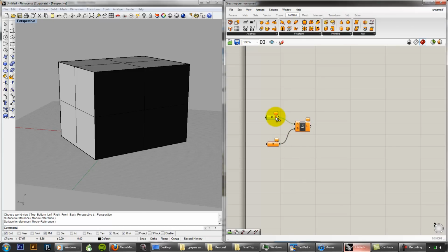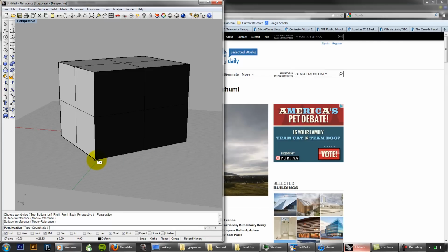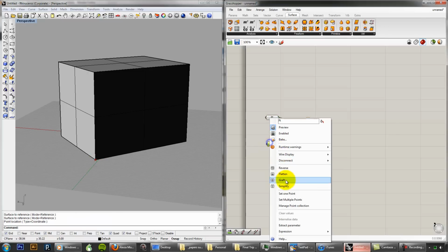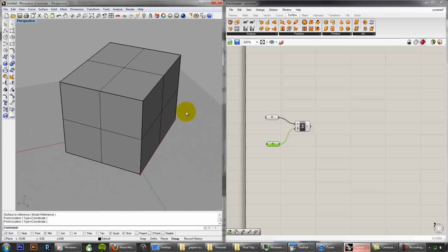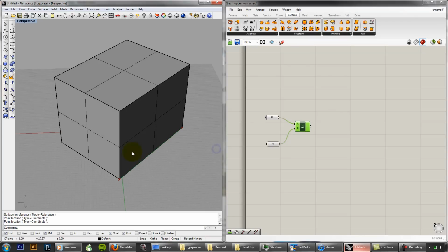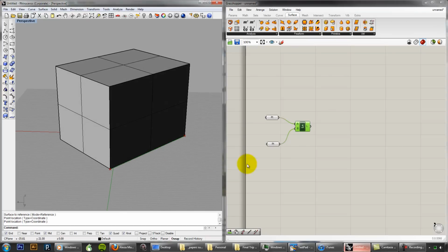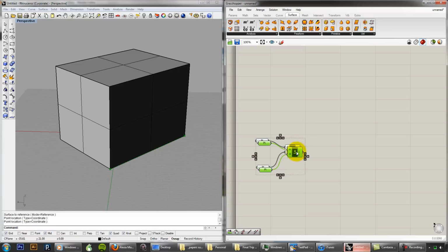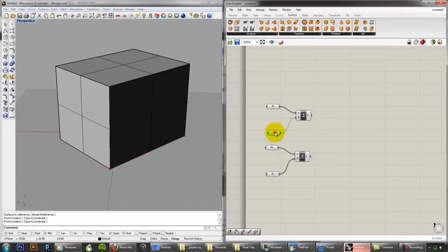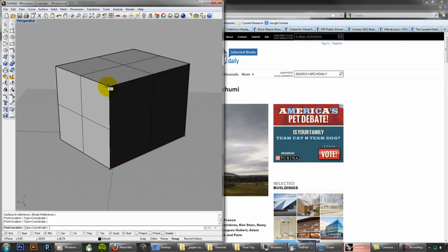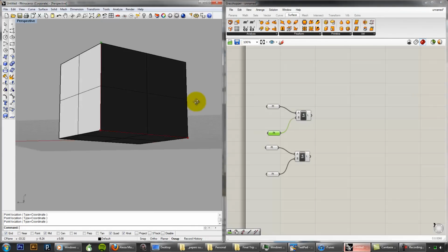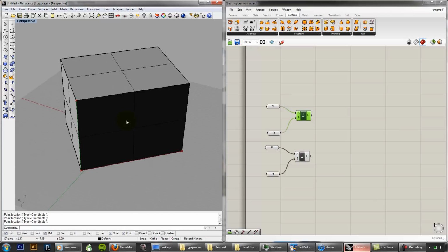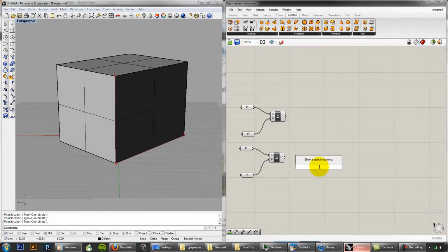And this is almost silly, but you take a point, and you can set a point by clicking an object. So if I have the endpoint selected, I can just click, and I can select another point, and that essentially gives me a line that I define manually, so it's kind of the edge of the surface that I define. And then I can do something similar if I wanted to get the height of this, and I could just take this point and redefine it as this, and that actually gives me the edge. I don't know if you guys can see that on the video, but this edge, and this gives me the bottom edge. Then I can go through and do something like divide curve.